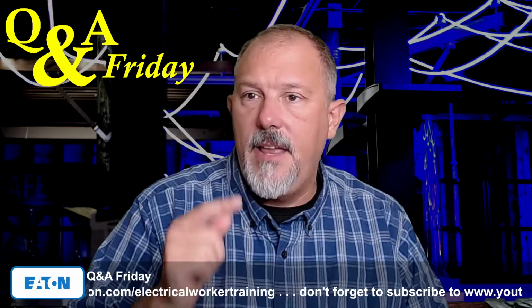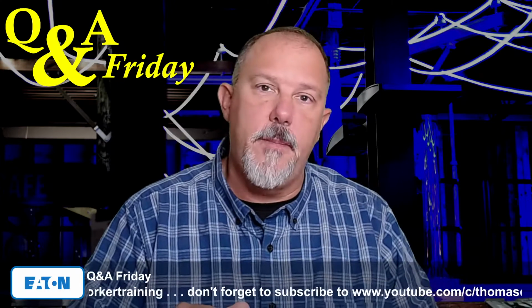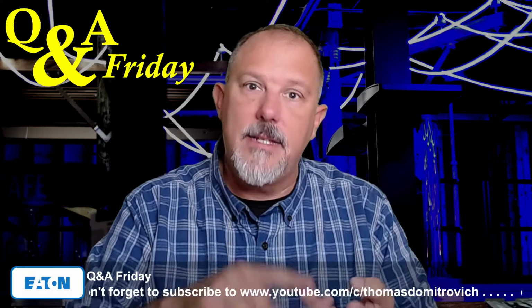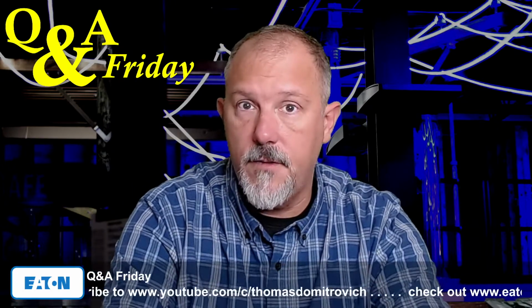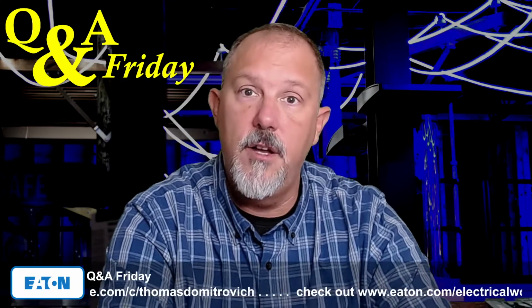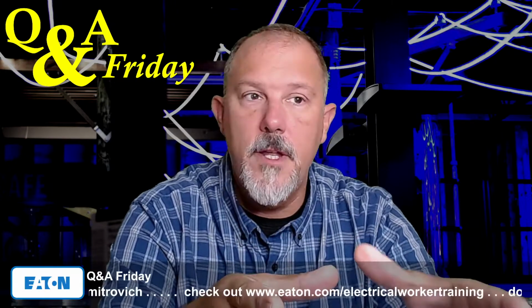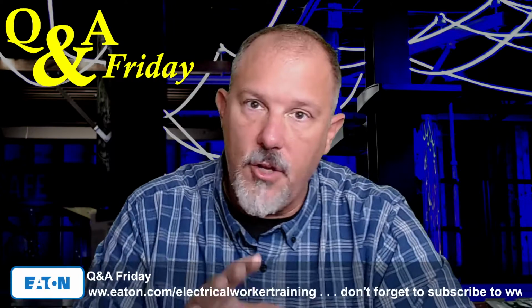I would say that if you want to understand the fundamentals of short circuits, short circuit current ratings, the capabilities of the devices. So equipment has interrupting ratings from an overcurrent protective device perspective. They have short circuit current ratings from a capability to withstand the current flowing through them. So voltage ratings, anything that has to do with a rating of a product that you're going to be installing.